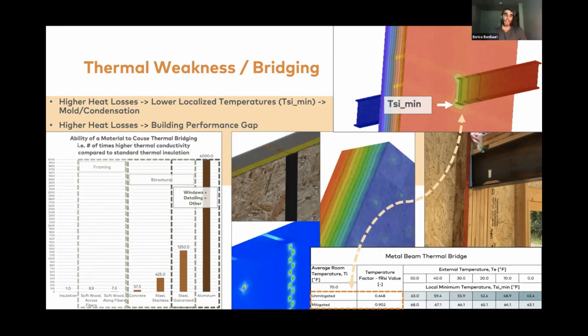Here you see some modeling that we've done on some different types of assembly. In the center, we see a 2x6 wall insulated with ZIP R sheeting, so supposedly continuous polyiso insulation. And the red dots that you see at the bottom, so many of them, are the thermal bridging caused by the nails. The more you get close to zero energy consumption in buildings, the more every single tiny thing matters. So all those nails that we model according to the spec sheet of that insulated sheeting do cause thermal bridging.